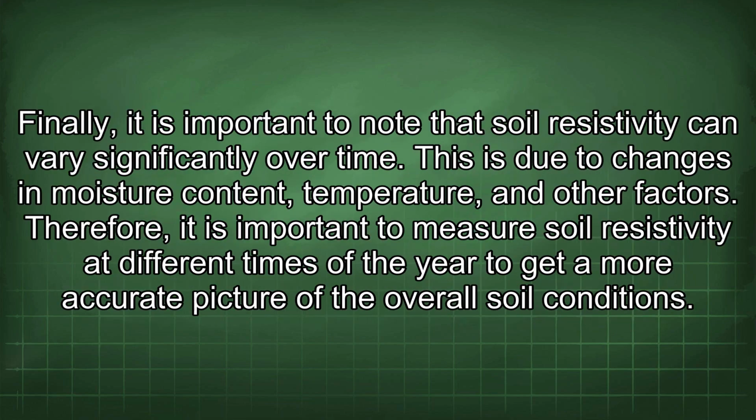Finally, it is important to note that soil resistivity can vary significantly over time. This is due to changes in moisture content, temperature, and other factors. Therefore, it is important to measure soil resistivity at different times of the year to get a more accurate picture of the overall soil conditions.